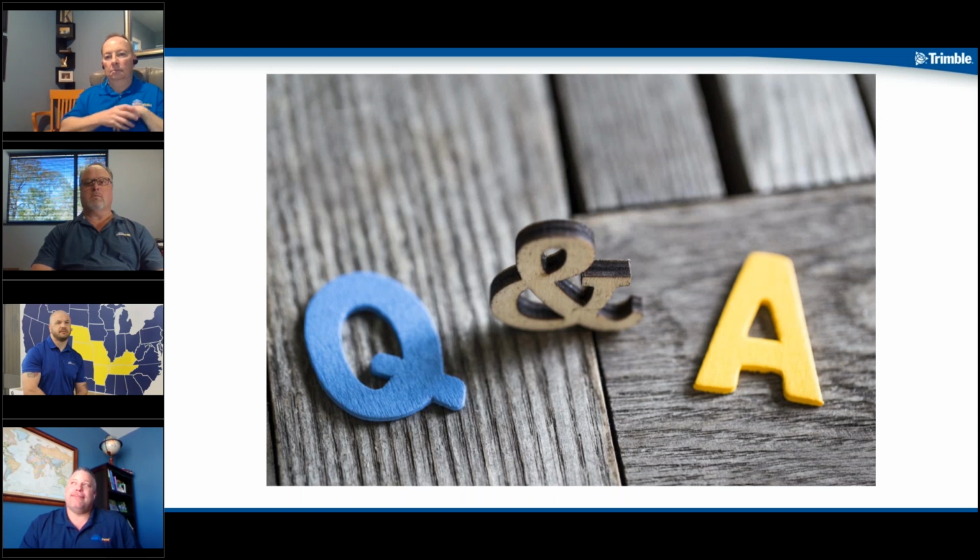So laying out, the problem with that is accuracy. You're missing a key component when you're trying to lay out a curve or an arc or any type of curved surface. If you don't have that radius point, that's pretty tricky. I mean, you can create an arc between just two points, but you don't know how much that arc has to bow or how shallow that arc needs to be.